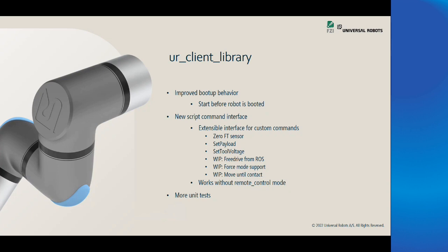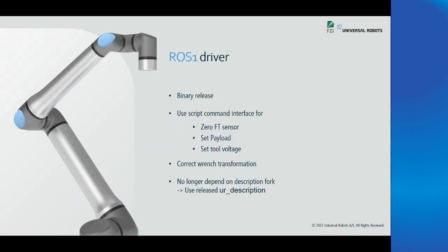In the ROS1 driver, we are almost there at the binary release. We first had to put a lot of effort into releasing the description, which has been hanging around for a couple of years. So we're pretty happy that this worked out now. Then we have the command interface in place in the library, and that's been integrated into the ROS1 driver already. So we can zero the force torque sensor, set the payload, and set tool voltage, as I just said.